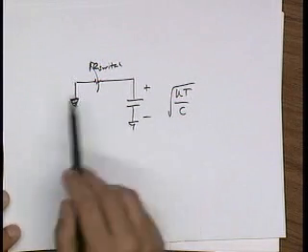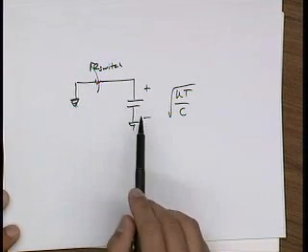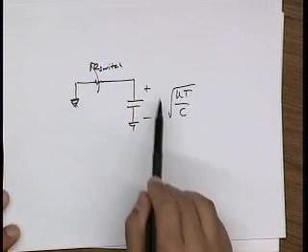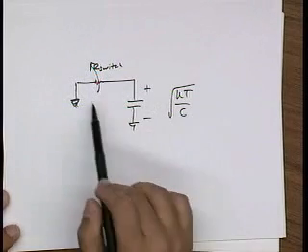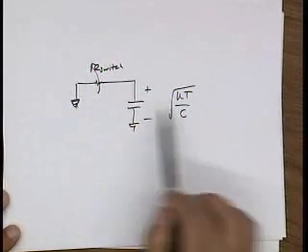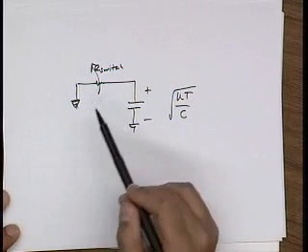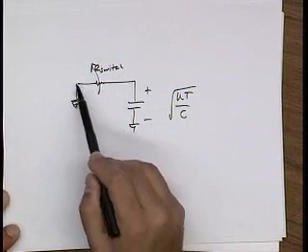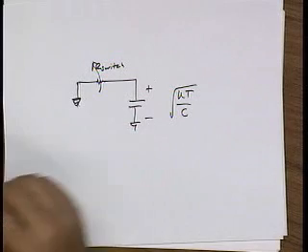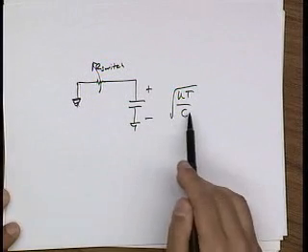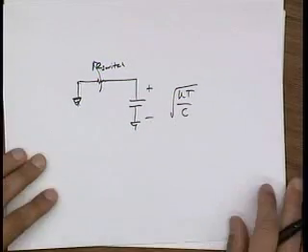This is no different from the sampling problem that we looked at several lectures back. The neat thing is that, as before, the answer is independent of the resistance of the switch, right? It only depends on the capacitance, because the smaller this resistance is, the wider band this is, and the more noise we integrate, right? And so, again, this is a philosophical question that you can think about maybe when you're walking home today. What happens if I have an ideal switch, like you suggested? If the switch has 0 resistance, final answer doesn't depend on the switch resistance. So what's going on?